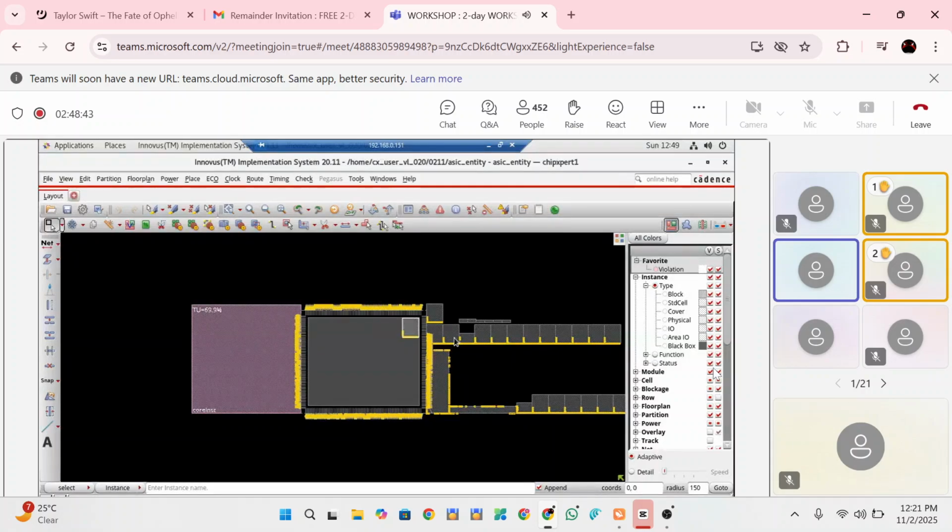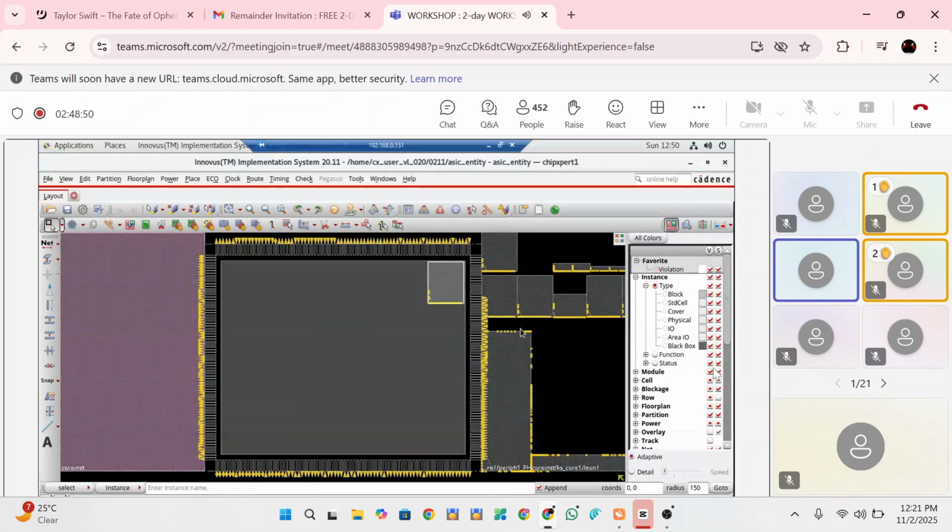So this is how the basic physical layout looks, with some values we have taken into consideration. And these are the different RAMs and ROMs and different peripheral connections for this chip. All of this outside the box are the pins to connect to the motherboard. They are called the I/O pads. The pads will have a metal layer that connects to the package pins, and they will connect to the motherboard. Now we will start.